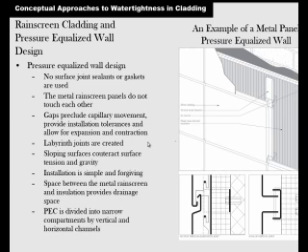The labyrinth joints are created. You can see that. The sloping surfaces counteract the surface tension, so it's sloped downward. The installation is simple and forgiving, meaning you don't have to be a master of rocket science to do it. The space between the metal rain screen and the insulation provides a drainage space. And the pressure equalization chamber, which is the PEC, is divided into narrow compartments by vertical and horizontal channels.